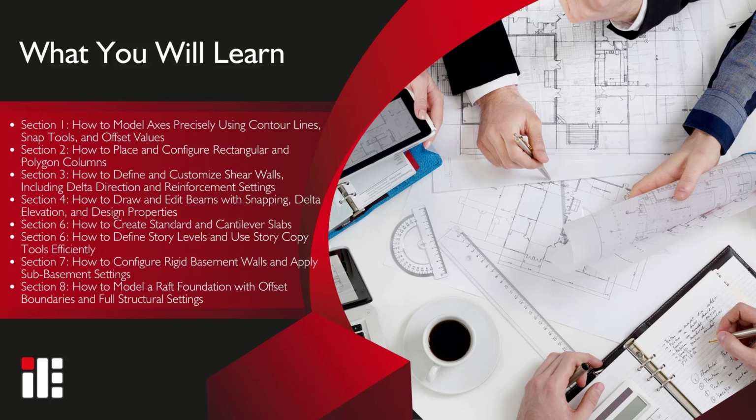Next, we'll define shear walls with dynamic delta control, group wall assignment, and reinforcement design options. You'll learn how to draw beams across axes and columns, adjust delta elevation, and apply key structural and reinforcement settings. We'll continue by creating slabs, both standard and cantilevered.